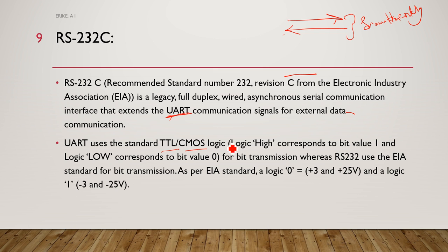Now, the UART that was referenced here uses the standard transistor logic, or CMOS logic. It's an extension of this anyway. In CMOS logic, a logic high usually corresponds to a bit value of 1, and logic low corresponds to a bit value of 0. But it is not the same thing in RS232.